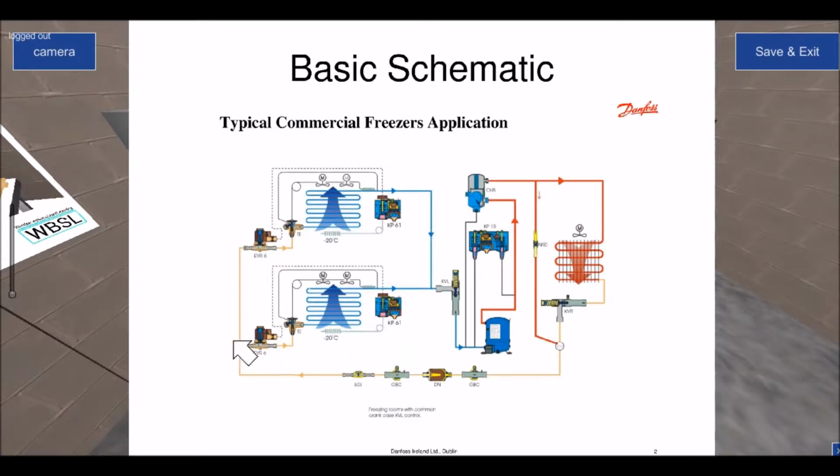Okay, other accessories: solenoid valve used to pump the system down. So in other words, once that solenoid valve is de-energized, refrigerant won't go into the evaporator, and if the compressor continues to run, the vapour is pulled out of that evaporator back into the compressor, discharged into the condenser, into your liquid line, and as far as the solenoid, it won't go any further. Eventually the low side of the system runs out of vapour, and your LP pressure switch is set to make sure your compressor and your system doesn't go below zero, so it will break the electrical feed to the compressor and the compressor cycles off.